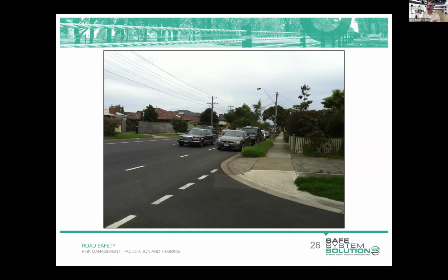Yeah, that's right. Generally, road authorities talk about convex mirrors as a last resort, when you've absolutely tried everything else, due to the challenges they present associated with reliance on it, maintenance of it, the sometimes distorted images, and lack of ability for people to utilize them in an appropriate manner.